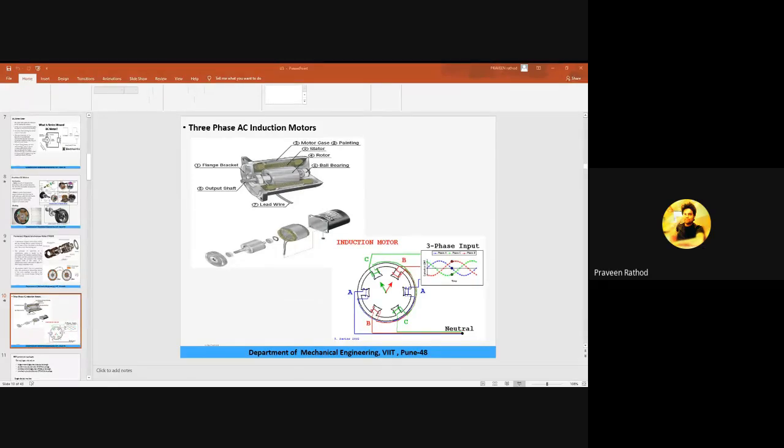So when traveling along a curved path, the differential comes into the picture. What does the differential do? It avoids the slip of the tire. Whenever we are moving in a curved path, the outer wheel moves farther than the inner wheel. So what happens if the differential is not there? It will not balance both the wheels. That's why nowadays also it's very important to use a differential.